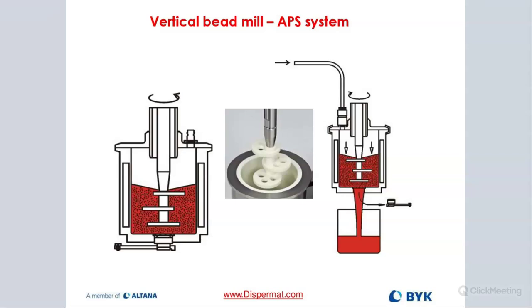So when I'm done milling, I have an air socket, or air connection, in my cover that allows me to purge my container with air or nitrogen or any other inert gas, and then push out the material into the container below, which catches all the milled material once I remove the drain plug. So a really easy, efficient way of milling.